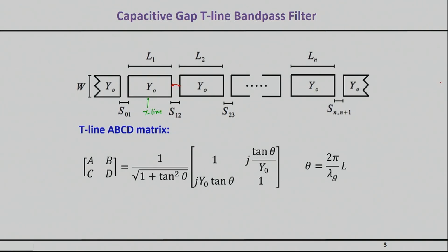This is going to be our input transmission line right here. Let me actually use my green marker. So this will be my input transmission line, and this will be my output transmission line. And typically, the width of this will be such that this transmission line here is a 50 ohm impedance, because usually the input and the output will have to be 50 ohms.